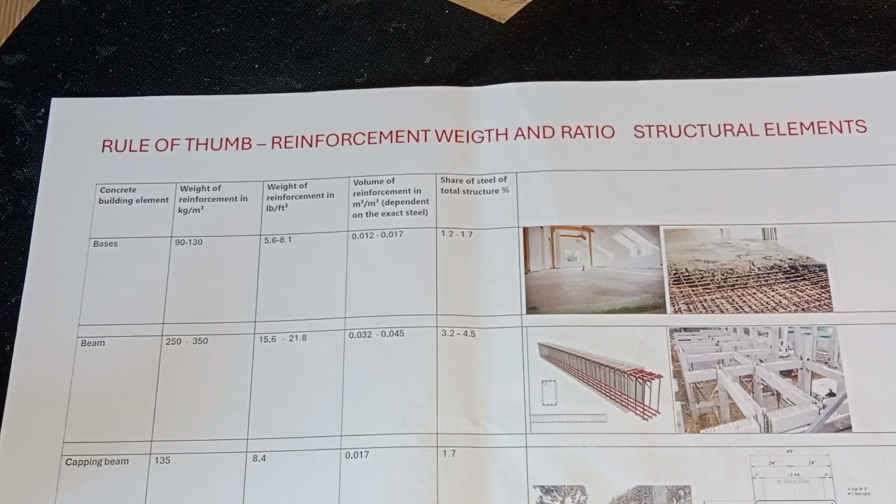concrete. Always experienced design engineers and senior design engineers, when going to check the construction drawings, they are not going to check the applied loads first. First, they're going to check the reinforcement ratio in different structural elements, let's say beam, column, slab, foundation, or all these elements. And if it's in the range, they generally accept the range. And if it's out, they're going to check the next step, why it is out of the range and how